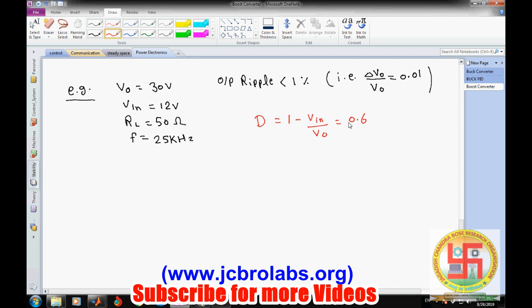Very straightforward. Then the minimum value of L can be given by this. L should be greater than, because in this case RL is given, D into (1 minus D) square into R divided by 2F, and it comes out to be 96 microhenry.